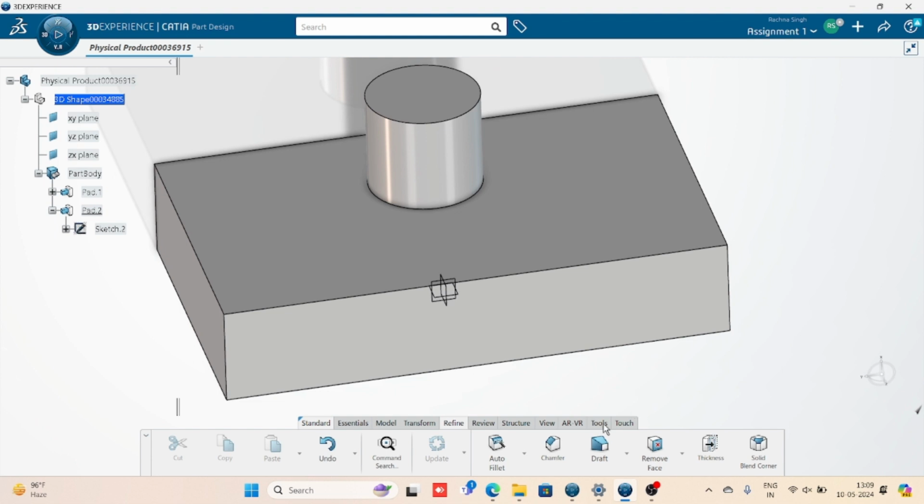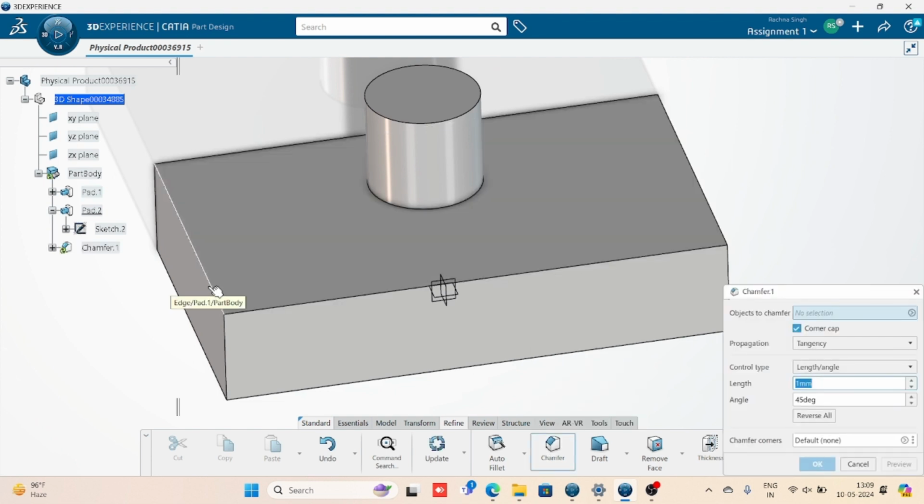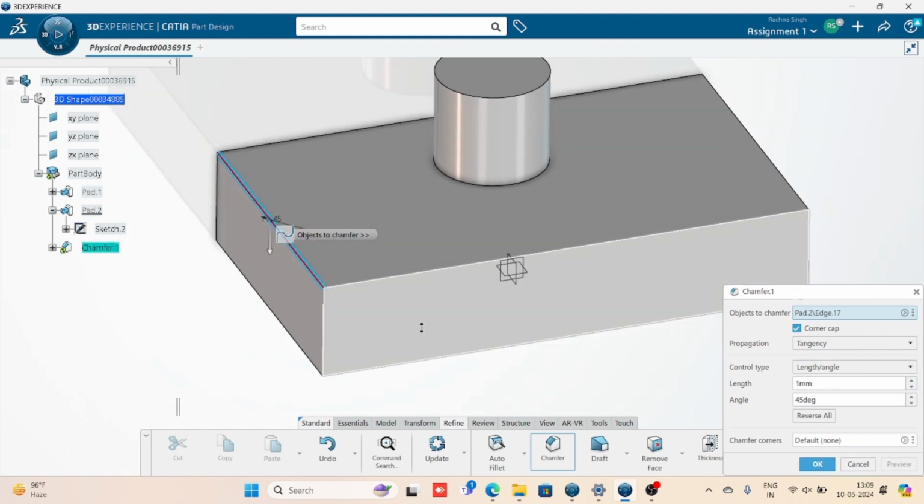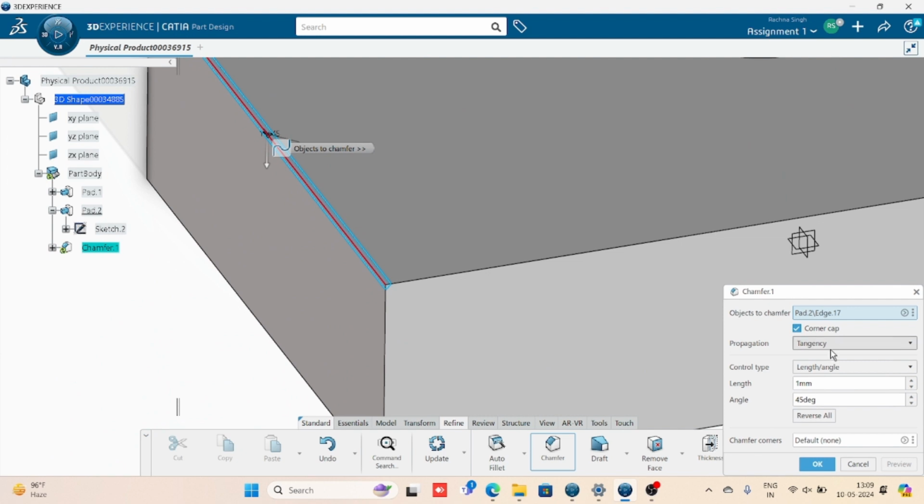Now similar is the chamfer command. Chamfer is where we don't want a round corner but we want a chamfer. In that case we can use this chamfer option. In this chamfer option we have possibilities, like if I know length 1 and 2, or chord length, or height and angle.